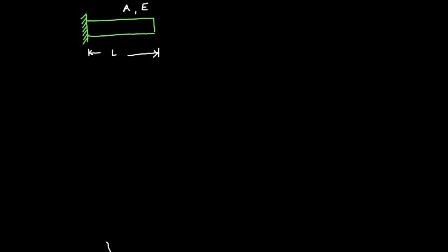Now, what is this bar being subjected to? This bar is subjected to a uniformly distributed axial load that is represented by these small red arrows. The magnitude of this uniformly distributed load, that is the rate of loading, is given as q. Its unit can be Newton per meter, Newton per centimeter or Newton per mm. You just have to take care of the units when you do real-time example problems with real values.